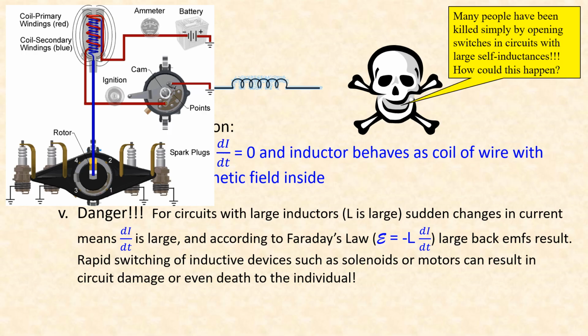The goal is for this large voltage to be induced across the gap of the spark plug. But if for some reason the large voltage were to be induced in the gap within the switch itself, this could be dangerous to a person coming in contact with the switch. Now, the likelihood of human contact with a switch in the distributor cap may be remote, but expand this idea to a circuit in general, a different circuit where a human being could come in contact with a switch for which a large voltage was induced.